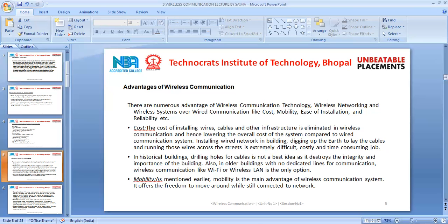One of the ways this is particularly obvious is when driving in a car and listening to an FM radio. At certain points the signal will become distorted and appear to break up. This arises from the fact that the signal is frequency modulated, and at any given time the frequency of the received signal provides the instantaneous voltage for the audio output.